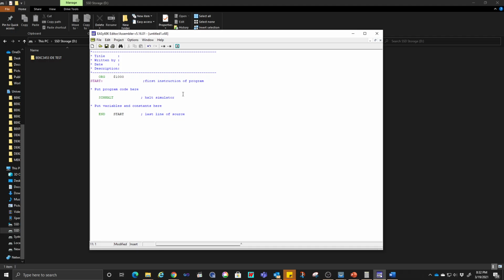Okay, so let's try to write a very simple code. I just want to remove everything here, and this one. So this is a very basic program where you have the first syntax lines and you have the end. Your program must be written between this head and tail. This is the body over here. Let's write one very simple command. It's maybe move.B #$AA to D0.